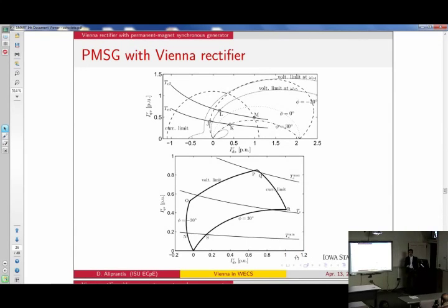So the question again is, in this type of drive, and we're actually the first ones that did this, I think, in the world: how do you select the current? What is the best way to select the current to give you the desired torque? The constraint is you need to be inside here. I give you a torque. What current will you choose to get that torque?